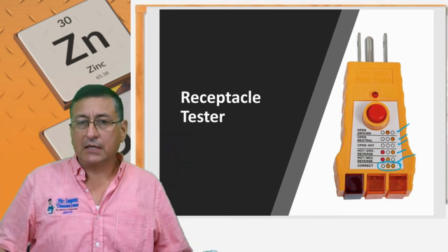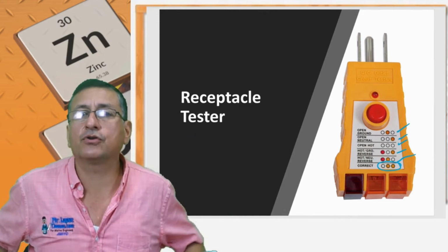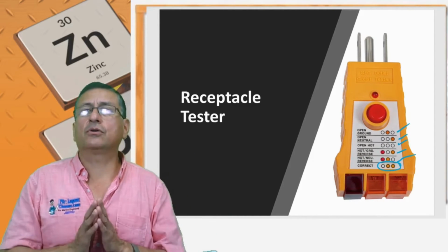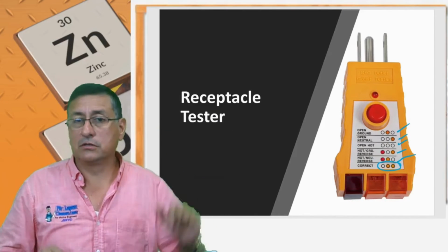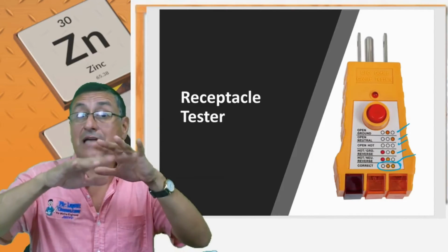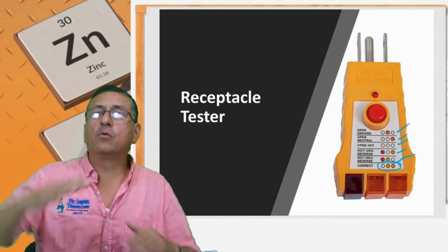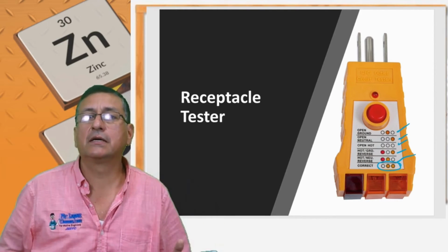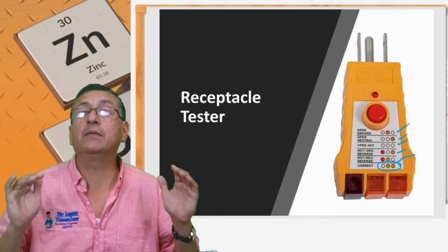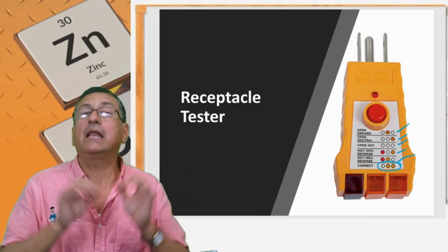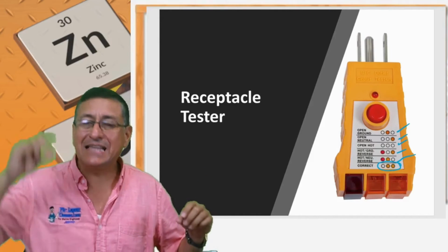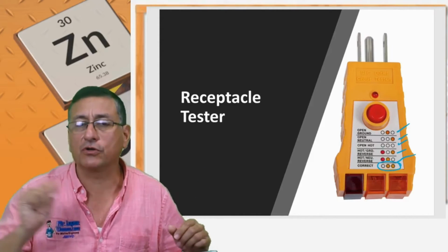Because remember, you can stop the corrosion by eliminating chlorine, salt, salt water accumulated in some areas, and also eliminating leaks of current. Both of them. The leaks of current accelerate dramatically the phenomenon of corrosion.